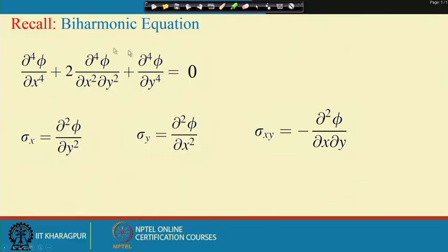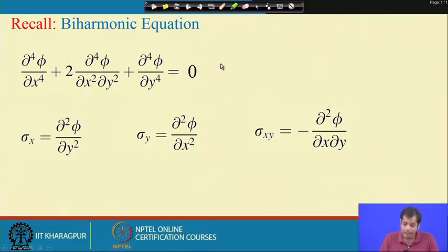If you recall, if we combine the governing equations and the compatibility equations and then define a potential, a stress function phi, which is called Airy's stress function, then the final equation we can have is this biharmonic equation. If we neglect the body force, then the form of this equation is the same for both plane stress and plane strain problems. So, let us now write this expression. This is the biharmonic equation. Let us now write this same biharmonic equation in terms of complex variables.